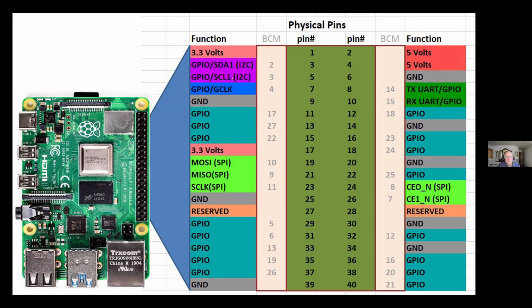4 wires can completely control 7-segment displays, 14-segment displays, graphics displays, all sorts of things. That I squared C stands for inter-integrated circuit connection. Inter-integrated circuit is what the IIC is. So that serial bus will control a lot of different things. Next, this SPI bus is serial peripheral interface. A lot of other chips require it. It is a 3-wire, much higher speed bus. So again, power and ground and those 3 wires, 5 wires total, do the whole job.